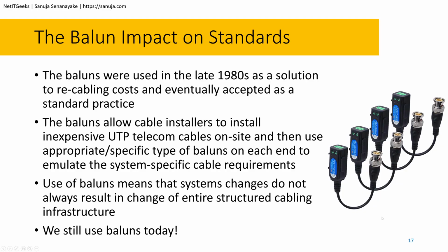For example, these are modern day baluns that are being used on a CCTV system, where CCTV cables are coax, but the final connection of the CCTV onto the equipment is not coaxial. In that case, you can use a balun like this, and they are still used today in even companies like Walmart, right? Walmart's CCTV system is pretty old actually. They don't use the modern day CCTV because it's a cost cutting thing, right? They still have the CCTV, but they use baluns like these ones to make it work. So balun stands for balanced unbalanced. So basically it connects two different types of cabling structures.